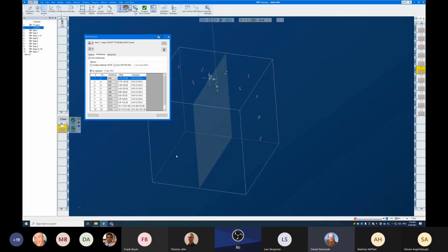So if you are using Tool Edge, it is possible for lead in and lead out moves to be trimmed out if their contact point would have been trimmed out by material. So that should be a problem specific to Tool Edge, and if you're in Tool Center, you should still get the extension that you asked for.